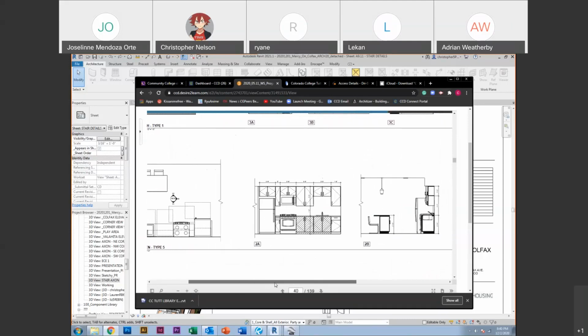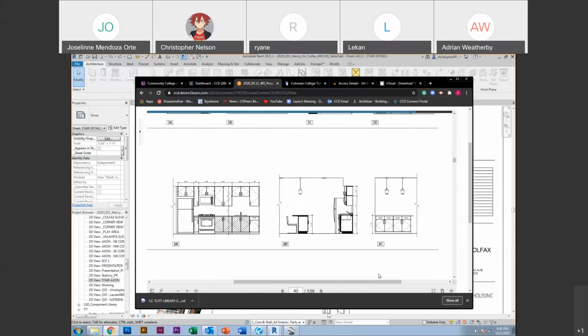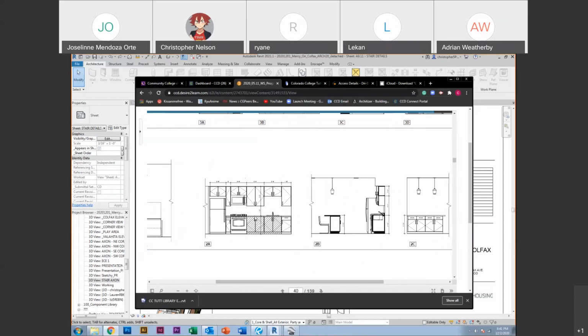He then did an elevation, and he dimensioned out 2'8" for the space from the wall to the fridge, a little 9-inch cabinet, 2'6", I can't really read it, but you dimension that, and you might dimension the height, which he did over here. Usually these are used to help contractors put the room together the right way. So the guy that comes in to build the casework can look at this and know what he needs to build. You're going to wind up doing these over and over again because they're custom per project.